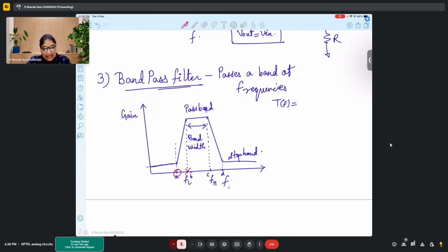Now again at C, the constant gain has started reducing. So if the gain has started reducing, that means again I have encountered another pole. And at D point, since that gain has stopped, it is a zero again. So you can either say 2 pole 1 zero system, considering that the rightmost stop bands are not required, or else you can say 2 pole 2 zero system, right?